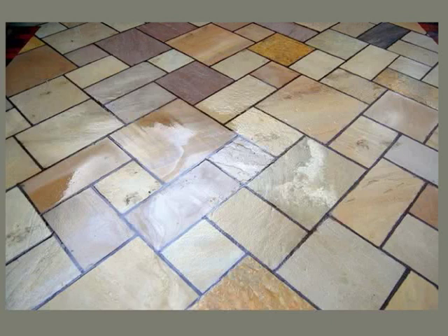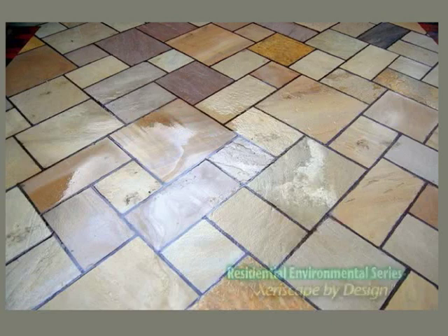The most formal and the most traditional way of laying stone is on a concrete base. So this picture shows the forms to pour concrete, and then we're going to put stone on top of it. This is the most expensive way to do stonework. It's also, in my opinion, when I'm running a construction site, one of the most stressful ways to do stonework, because I have to get everything exactly right on those forms. Because once concrete is poured, it's poured.